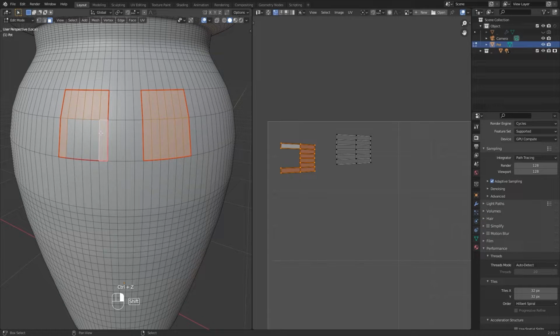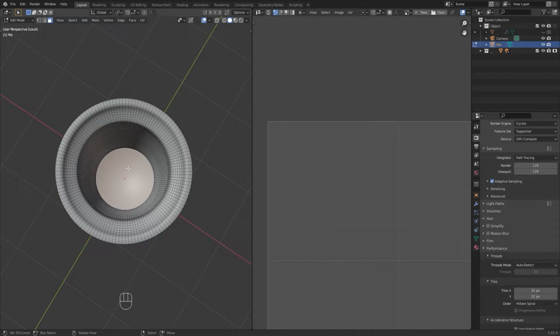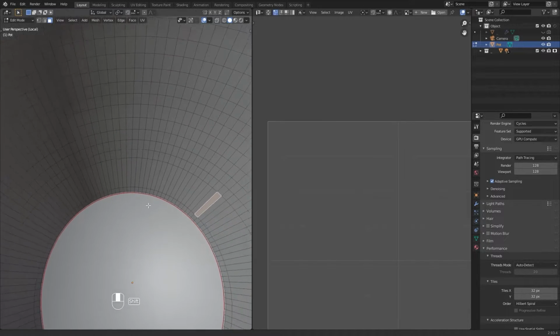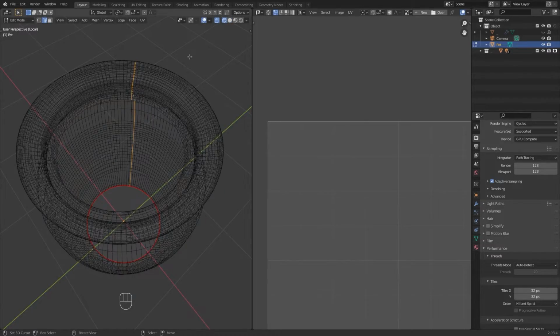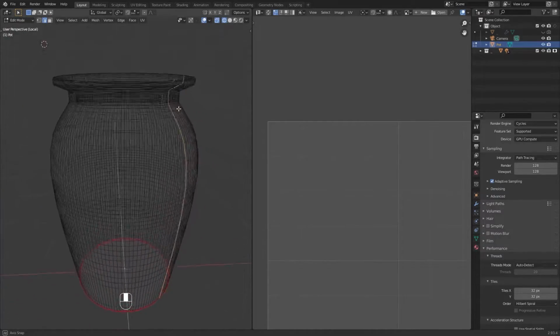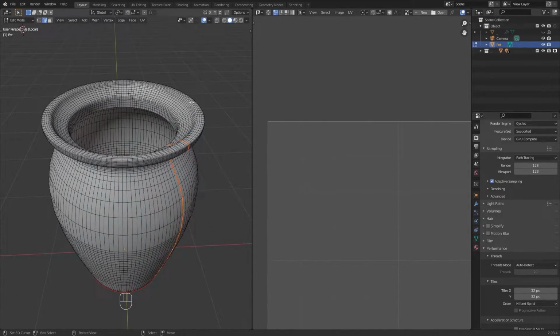Okay, now let's seam mark and UV unwrap this object the way we want. First, I will clear all the seams here. Now completely separate the bottom foot of this object. So, select this face and seam mark this. After that, switch to edge selection, then select a line with vertical edges on the inside surface, as shown here. You can use the hotkeys used here for this. Here is how the selected verts should look through the wireframe shading. Okay, now seam mark this. Now you can select this completely and UV unwrap.